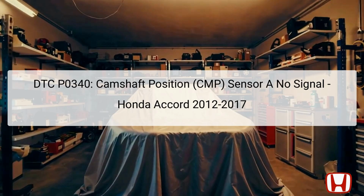The CMP sensor A plays a crucial role in detecting the intake camshaft timing and relaying pulsing signals to the PCM. The PCM relies on these signals, along with input from the crankshaft position (CKP) sensor, to accurately determine whether to advance or retard the camshaft timing for optimal engine performance. If the CMP sensor fails to send signals, the PCM recognizes this lack of input as a malfunction and subsequently stores the DTC for further diagnostics.